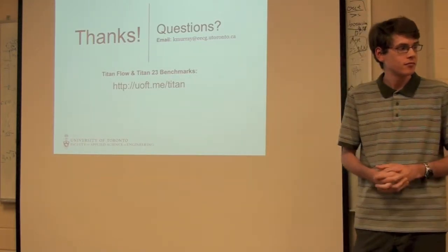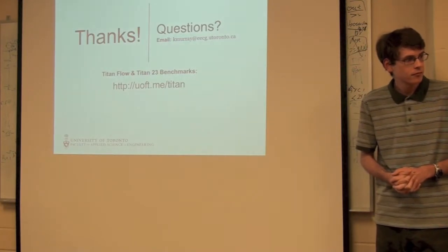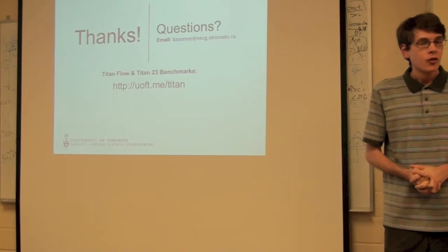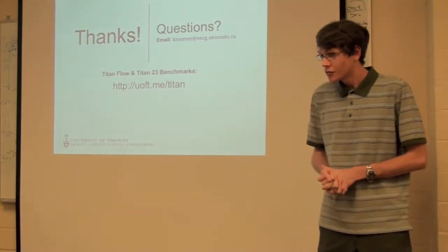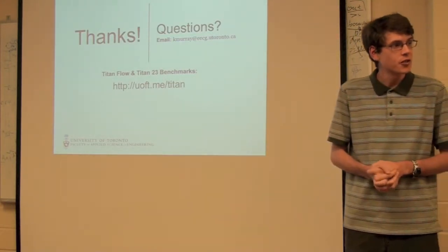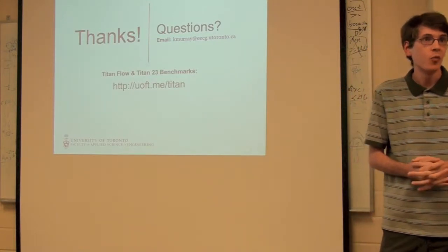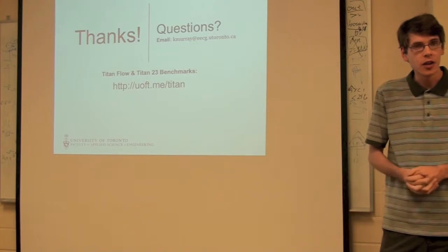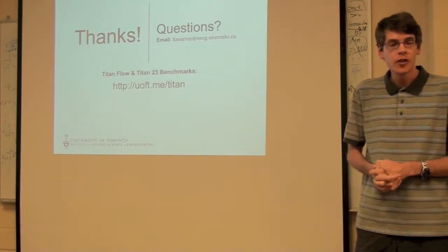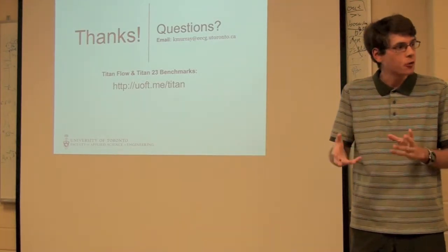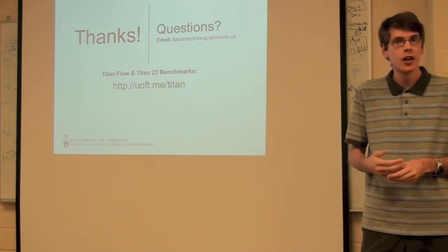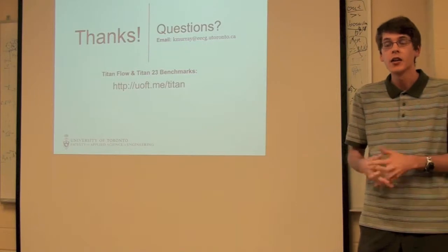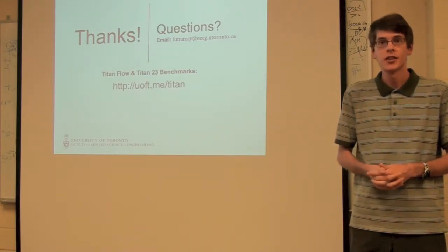So how big are these circuits? You had those pictures at the beginning, so how would they scale up? It's a good question. It depends on which benchmark you're using. The smaller ones of the 23 benchmarks would fill anywhere from 10 to 30% of the large Stratix 4 device. And for the two largest benchmarks, Quartus won't fit them, so they're bigger than any Stratix 4 device.